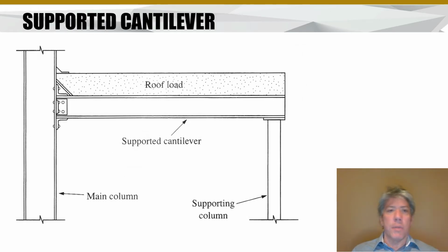Here's another example of a beam that is statically indeterminate. It's fixed on one end, so it's not allowed to rotate at one end, and it would be cantilevered except it's supported out at the end. So if we didn't have that cantilever, statics could help us solve for the moment back at the wall, but since we have that supporting column, things are a little different, right? Statics can't deal with that extra load. You'll end up with not enough equations and too many unknowns. One of the extra unknowns, of course, would be the load in that supporting column.